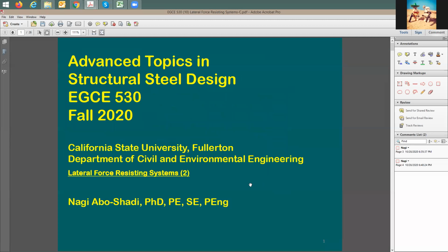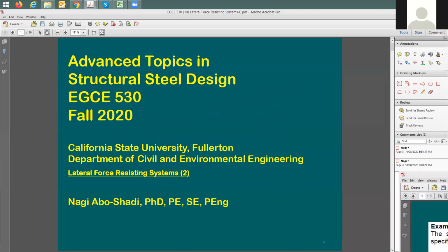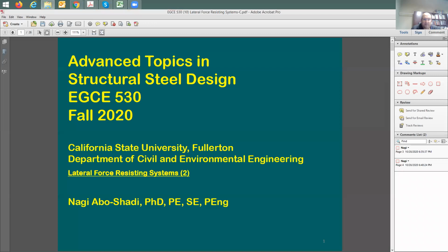Yeah. So what is the importance of this seismic design category? Let me ask you here. Anyone remembers? Why is the seismic design category important? Because we have to select the design according to that. For the selection of the building system. Yeah, and what else? Selection of the ductility factor. It's regarding the occupancy.